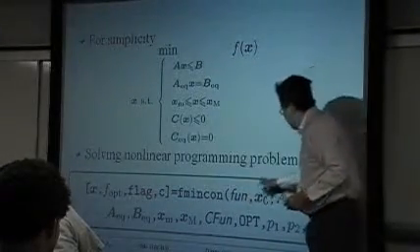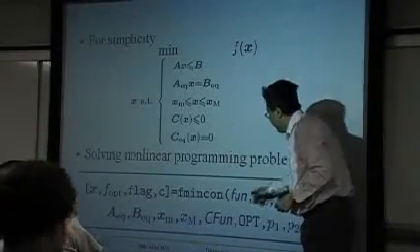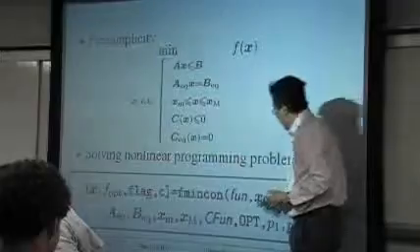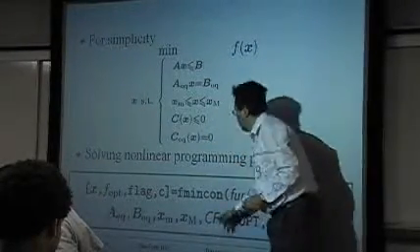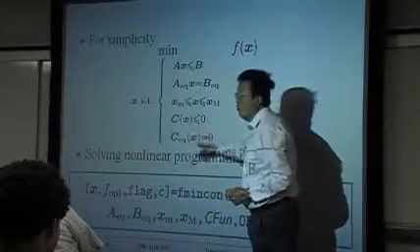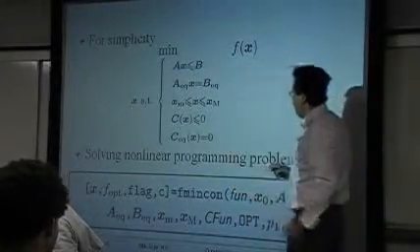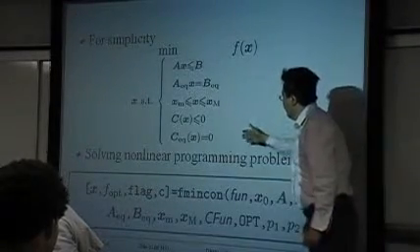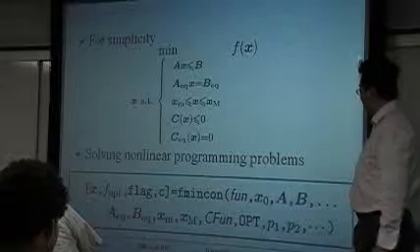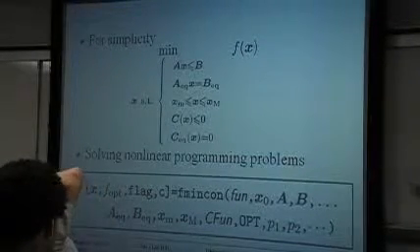And we have to specify an initial searching point. We also have to write a Matlab function for the nonlinear constraints, and this function should return two variables instead of one: one for the inequality constraint and one for the equality constraint. Then we can solve the problem immediately.